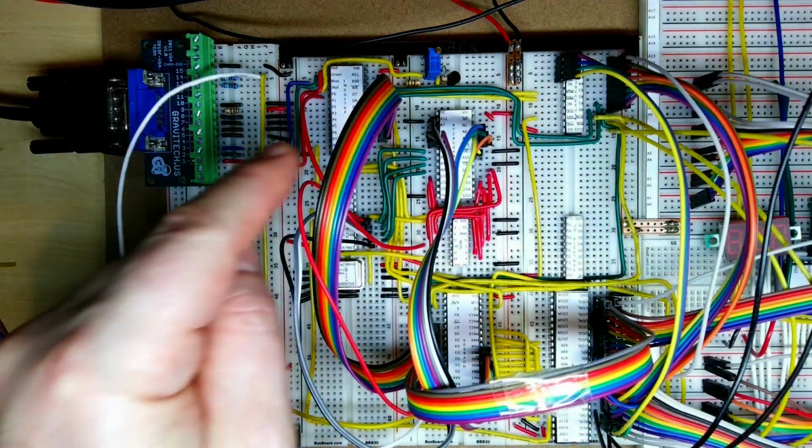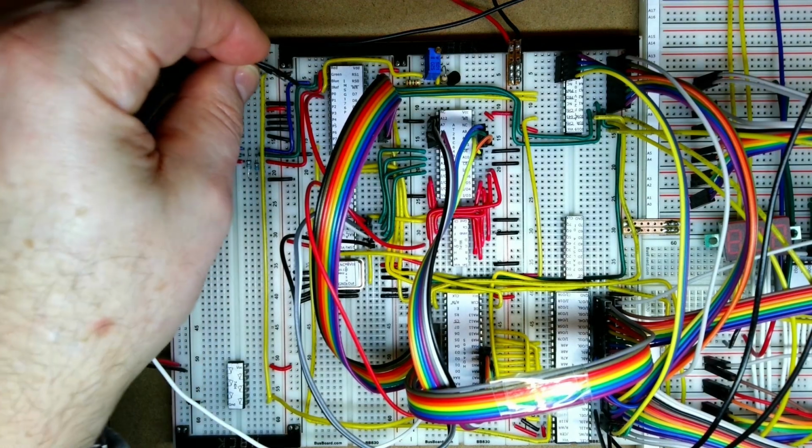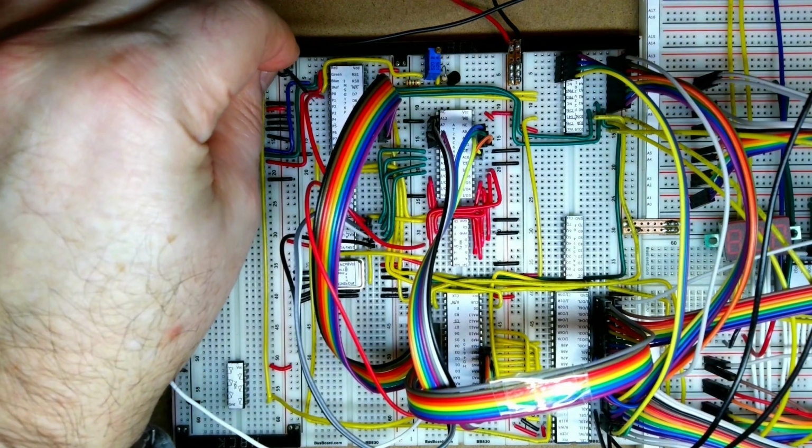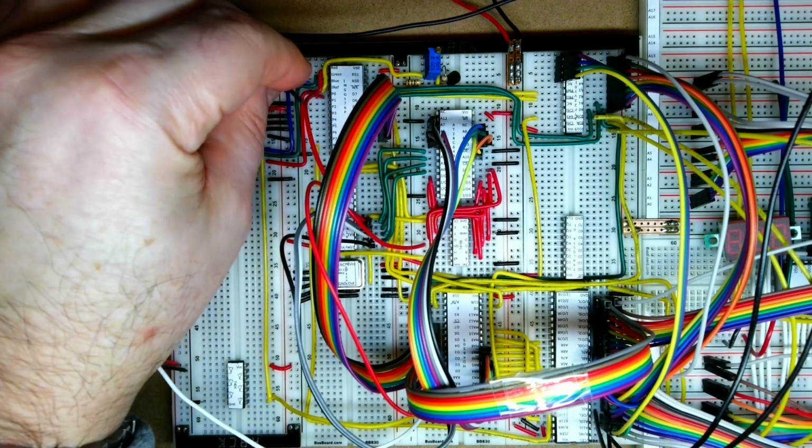And then also, although we've got one input into the digital analog converter, we really need to tie a lot of those inputs to ground. So I'm just going to put in a couple of ties to ground and then we will jumper the rest of the pins together.